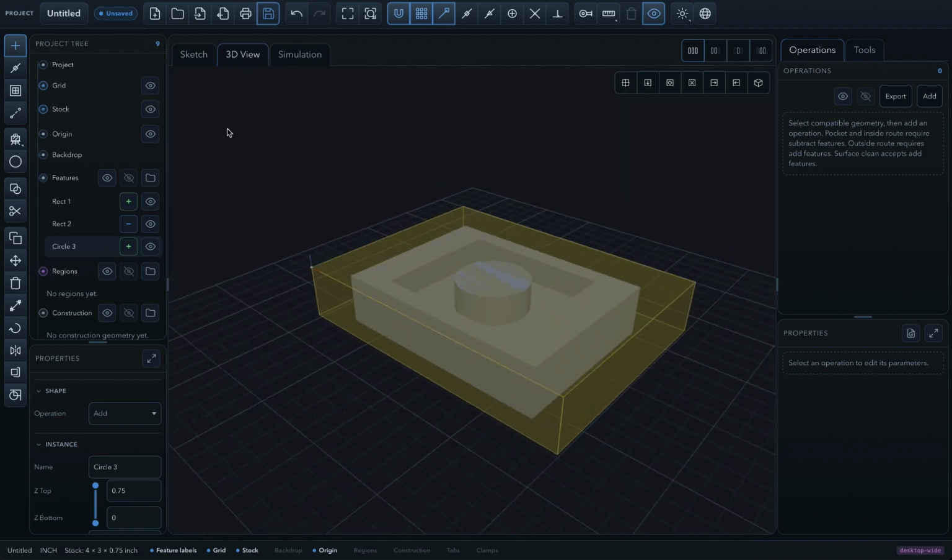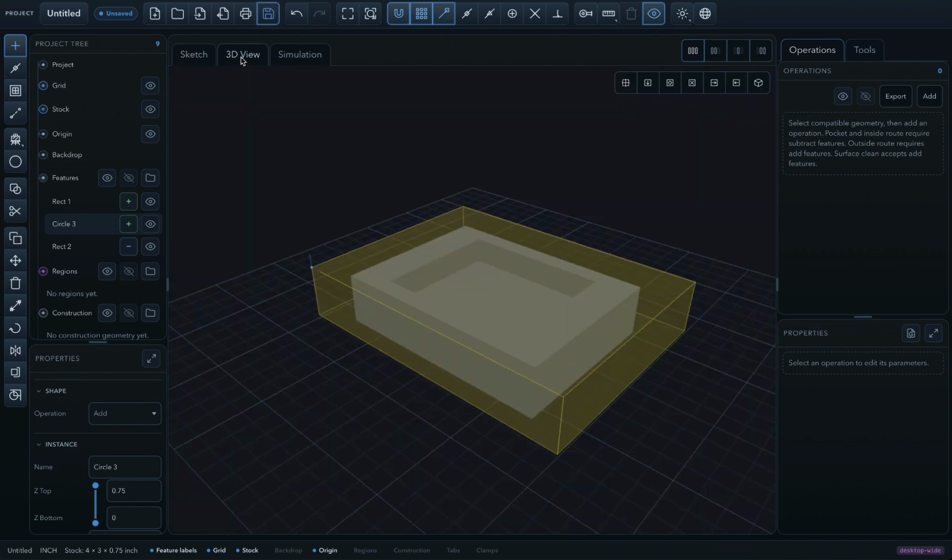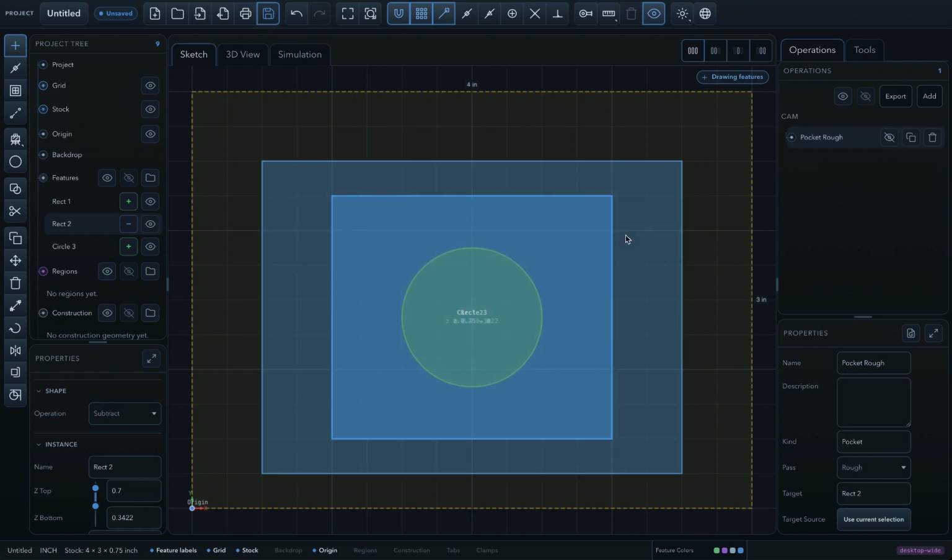If you drag it above the pocket and the two overlap, the later pocket removes material from both the base and the island. In the original order, the island is added after the pocket and can remain intact or fill part of that area. The same geometry has a different model because the operation order changed. Toolpaths still come from the operations you create, but those operations read the model boundaries and feature geometry established by this sequence. That matters directly to CAM.